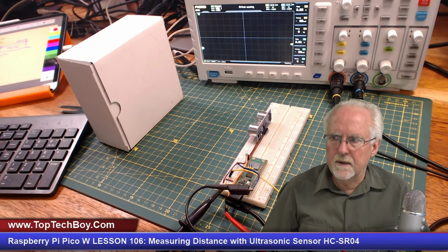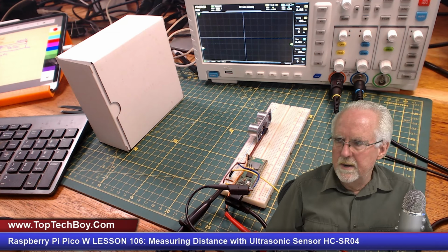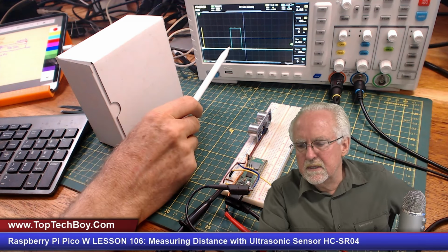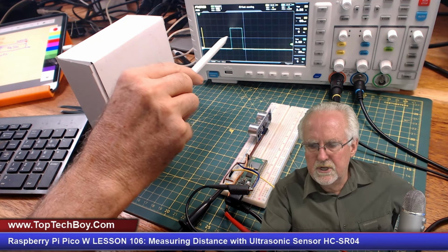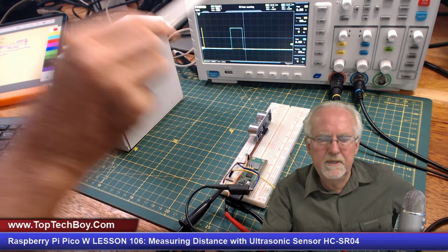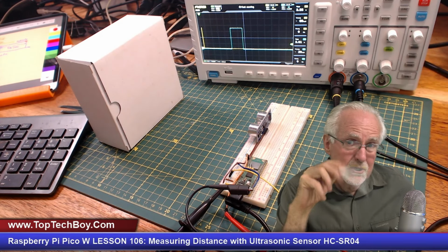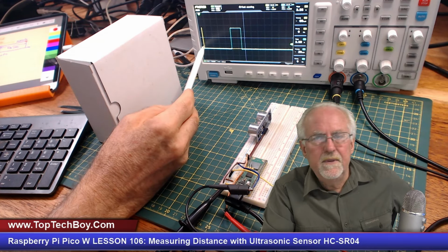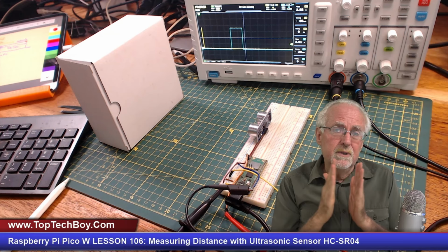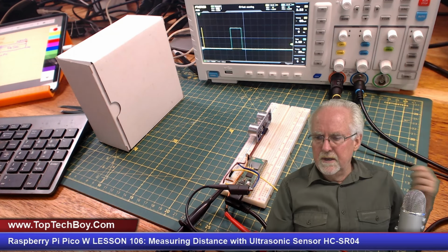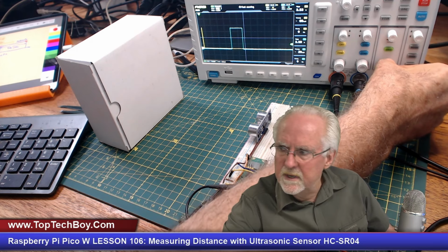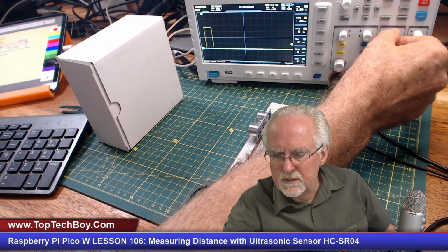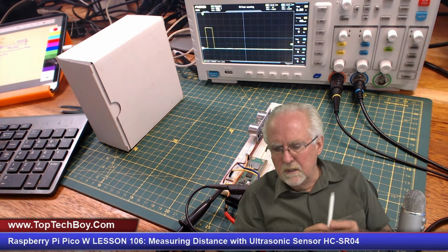So we're going to come here, and now I am going to run the program. And what you see here is my echo pulse, and it's kind of jumping around a little bit. It's not really completely stable. And remember how we saw our measurement numbers jumping around a little bit as well. Over here in yellow, this is the trigger pulse. But remember, the trigger pulse was 10 microseconds, so it was very hard to see. So I need to come over here and adjust my time scale.